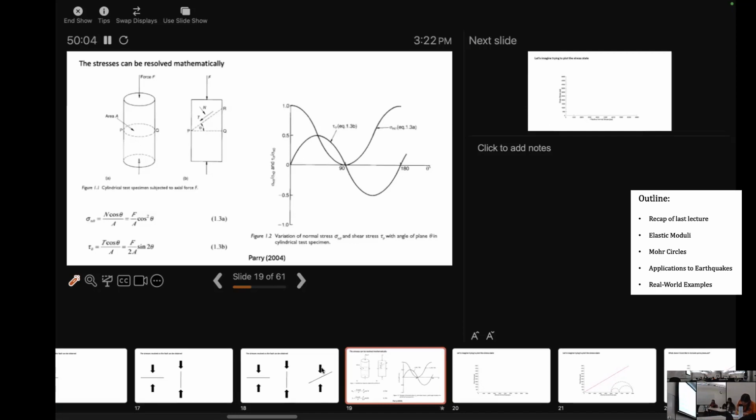We got a quick question, if you've got some time. Sure. So kind of trying to put this into injecting CO2 into the ground. That's what we failed to get to. Just based on very fundamental ideas, I don't really feel like I totally understand all this, but you're going to increase the pore pressure, which will reduce the effective normal stress, which then leaves the door open for shear to take over and have a little slip. That's exactly right, because we're changing the ratio. Exactly.